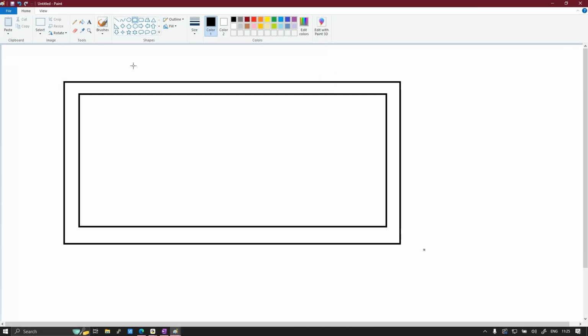A few terminologies are core area, or let's say core boundary. Internal to this core boundary, you will be having your macros and standard cells placed. Okay. The external boundary is called the die boundary or chip boundary.